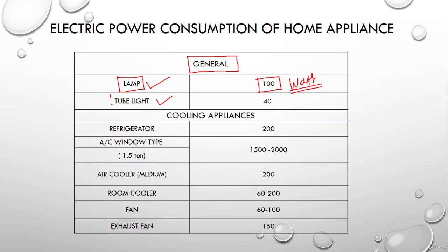Whenever we talk about the CFL tube lighting, it will consume near about 40 watt of power. Whenever we replace the halogen lamp or the sodium lamp with the LED light, it hardly consumes 15 watt. The more wattage we save in the corresponding home appliances, the more effective the solar home system will be. But that comes under the part of the energy auditing system.